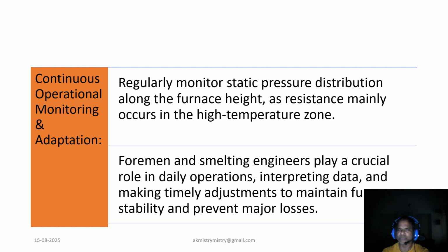So now coming to our next slide, which is about continuous monitoring and adaptation, on which we can say that monitoring the static pressure along the furnace height is very important, and most resistance is in the high temperature zone. Foremen and engineers must interpret data daily and adapt operation to maintain stability and prevent losses.